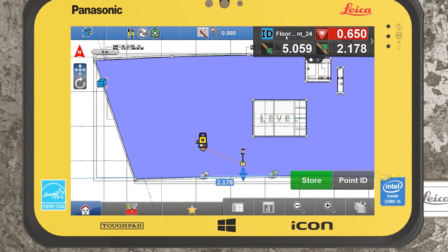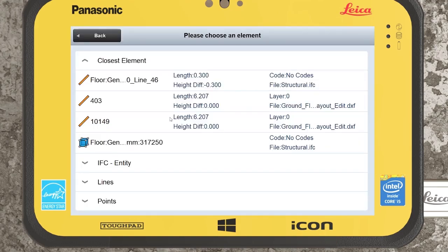and select start. And like when you're using the stakeout application, if we just jump back to the top view here, we'll get the same values: how far we are up the line from the start point, off the line in position, and in elevation. So I'll just move it over the line there. You can see there, just using the simulator, I can move my way back in and make it look like it's in grade there. So that's how we set out, guys.